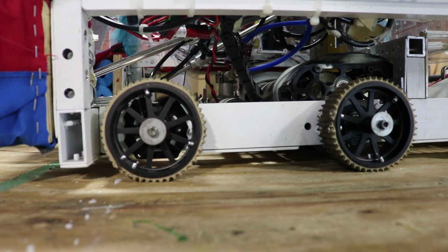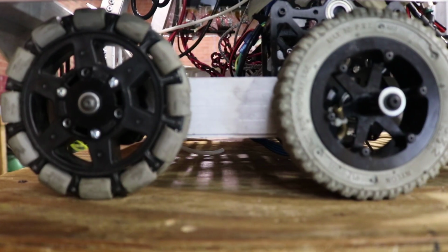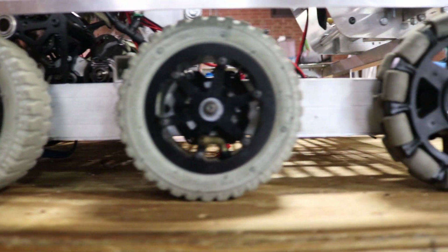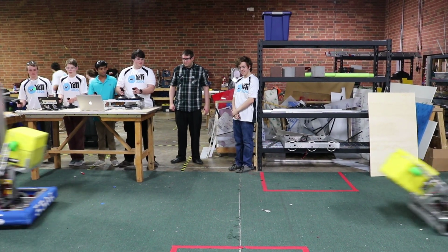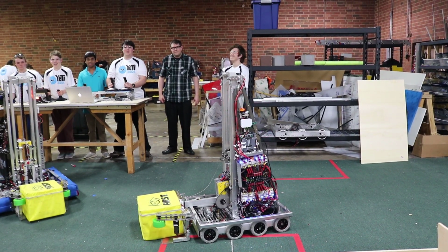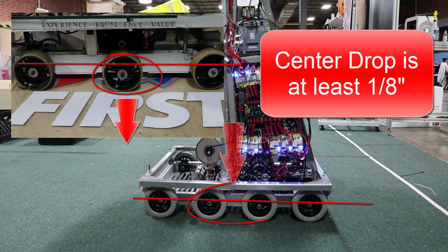but at this stage I want to pause and talk about drop centering in more detail. The middle wheels of a West Coast drive must be dropped if you're not using any holonomic wheels. If you are using holonomic wheels on the corners, you can disregard this step about figuring out the drop center and just place the hole for the transmission at the exact same height as the other axles and the Versa bearing blocks. Now, in our experience, the most common drop center is 1/8 of an inch, but this number is super important to get right.